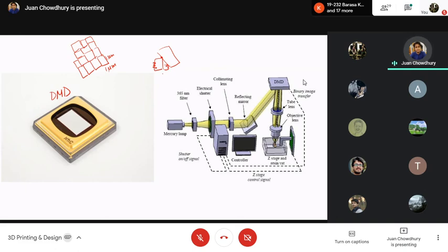Actually this concept is already established and projectors use them. So how does a projector work? A projector beams different color lights on this DMD chip, and based upon the deflection, if it is 100% deflected, it will usually generate a black spot. If it is 100% in alignment, it will create a light spot. So whatever comes in between will be treated as the difference in contrast.